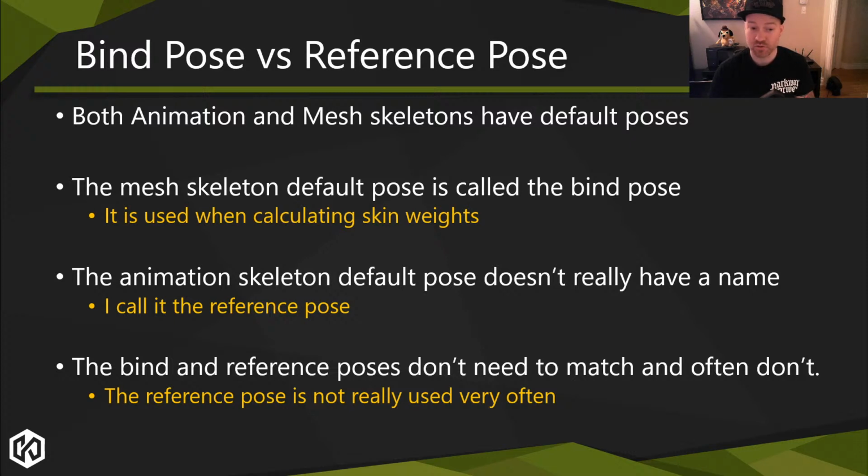Rest pose, Connor mentions, is another term for it. Rest pose is something that is used as well. Although, again, I've had tech animators and tech character artists confuse rest pose with bind pose all the time. This is a super confusing concept. I don't know how to fix the name. Maybe it's just animation skeleton default pose, mesh skeleton default pose. The animation reference pose is really not used that much in the game. It's sometimes useful, but in general, it's not. The bind pose is the one that's literally used every frame.